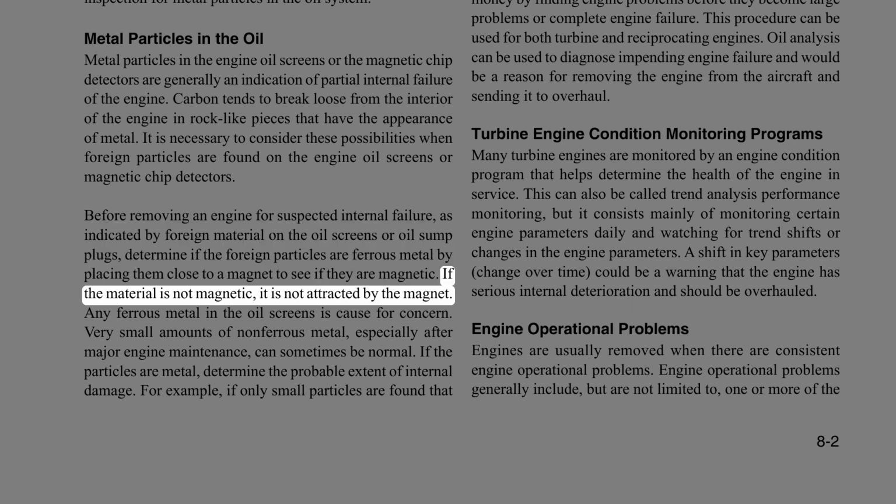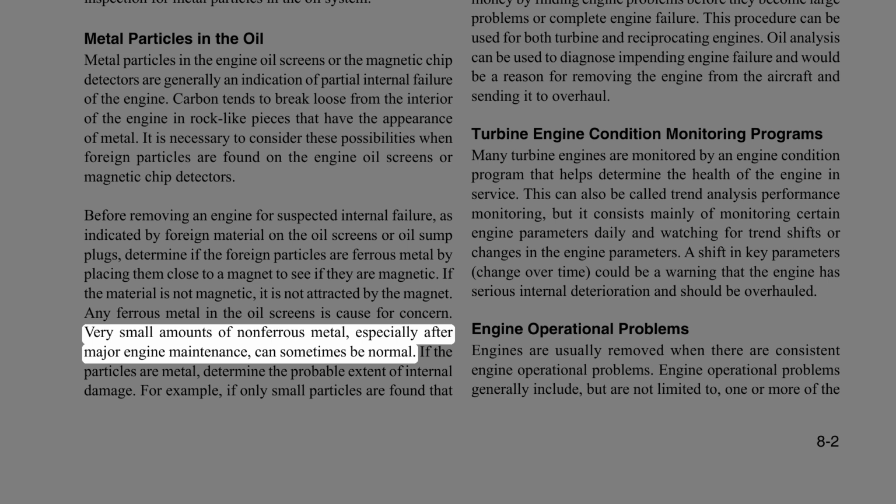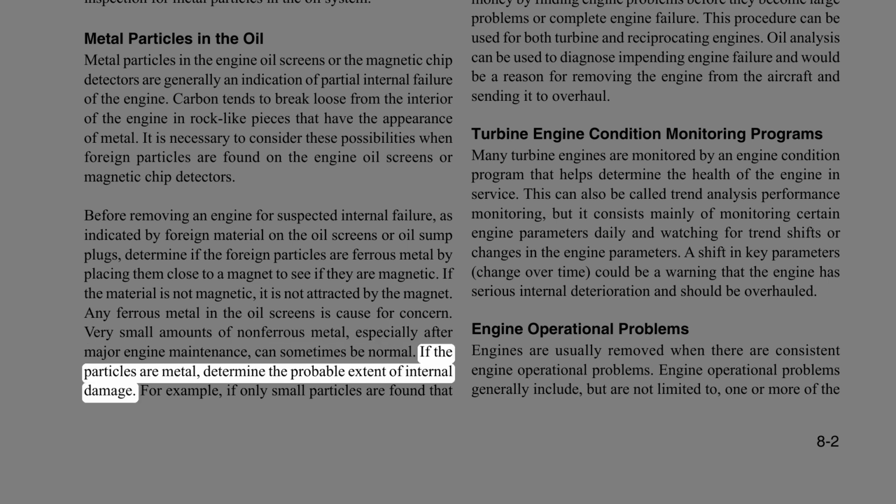If the material is not magnetic, it is not attracted by the magnet. Any ferrous metal in the oil screens is cause for concern. Very small amounts of non-ferrous metal, especially after major engine maintenance, can sometimes be normal. If the particles are metal, determine the probable extent of internal damage.